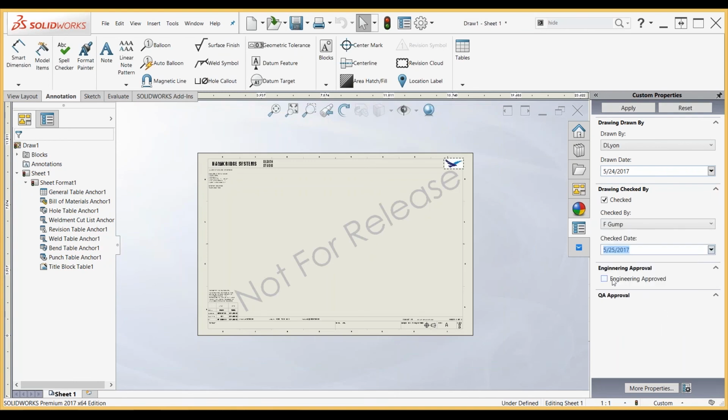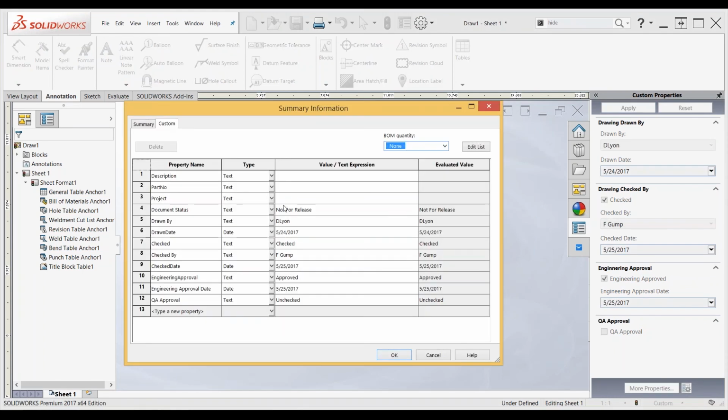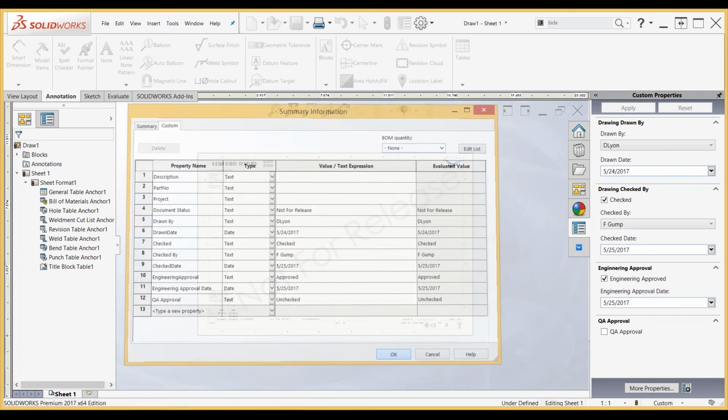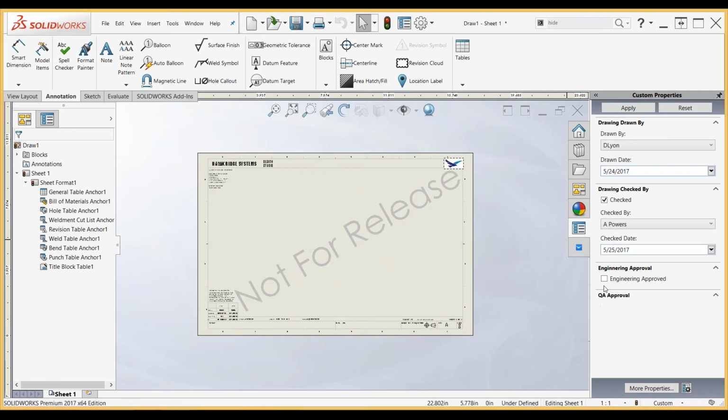And it's pulling information from an Excel file. So the list of values that I'm allowed to assign to that custom property are being pulled from sheet 1, E2 to E7 of this Excel file somewhere on my computer. Then for the date, I just grabbed a text box and set it to type date, so then that calendar propagates and you can grab that as well.